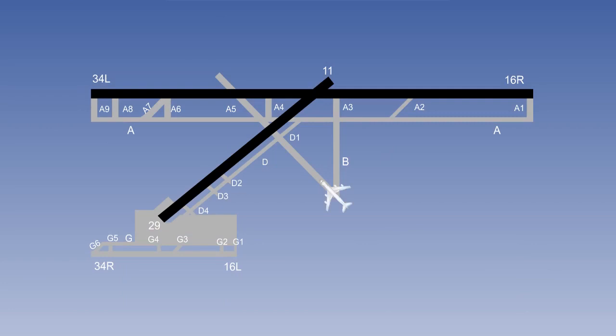The final part to GPWS is the runway awareness and advisory system, which was introduced to help reduce the number of runway incursions. The system has a database of all airport layouts, so combined with an accurate navigation positioning system, like GPS, it enables the system to know where the aeroplane is in relation to runways and taxiways. It helps improve a crew's situational awareness when in the vicinity of an airport by issuing various oral alerts during taxi, takeoff, approach and landing.